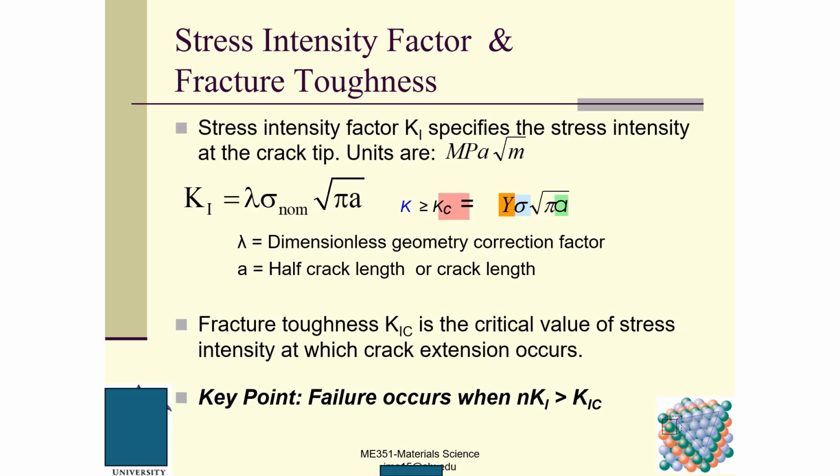The stress concentration factor is the result of having cracks and flaws in the material, so in the neighborhood of these impurities or flaws, we will have a high stress level. That is called the stress concentration factor. Now here is the stress intensity factor.